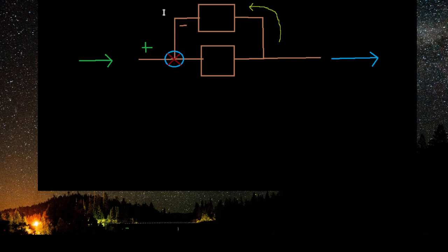The Nyquist criterion is a stability criterion. It enables one to determine the stability of a system. Closed loop stability can be determined with experimental data from the open loop system. The two plots show essentially the same thing. The Nyquist criterion, however, is more complete. If it indicates an instability, the system is absolutely unstable.